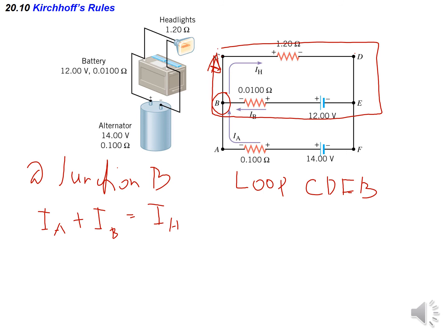In that case, let's solve for the total potential difference. Let's get the potential drop and the potential rise. I will be starting here. Again, for the loop rule, we'll just be using the formula IR. For the electromotive force, we just need to identify if it is a positive or negative electromotive force depending on the terminal.